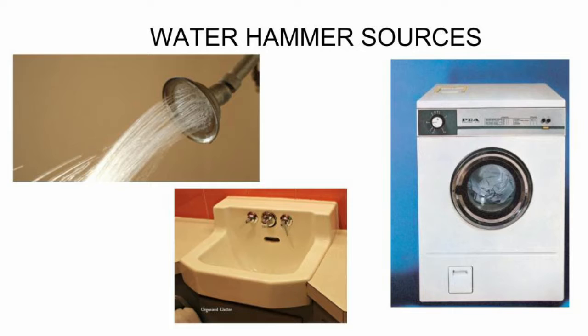It is noted that Ohio Building Code 1206.7 requires the water hammer effect to be controlled where quick-closing valves are present. An arrestor must be placed within a specified range of the manufacturer of the quick-closing valve. Some examples of this are in your dishwasher or washing machine.